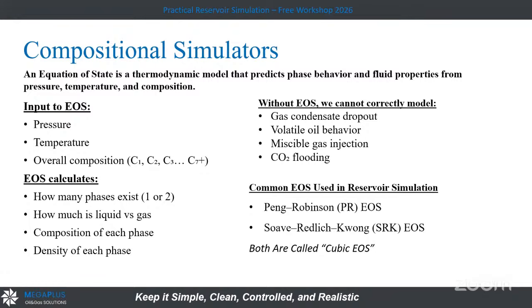If the water mobility is higher than the oil, we will add a polymer to the water, so we can alter the physical properties of the water and increase its viscosity, which improves the micro sweeping, and then the oil will be produced from the residual oil.